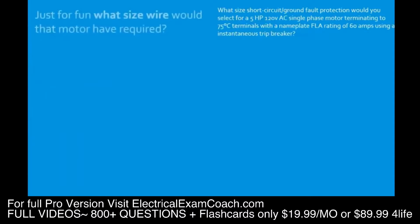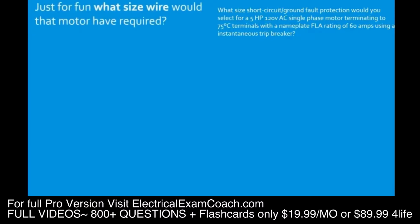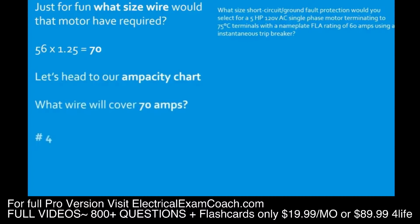Now, just for fun, we're going to take the same question and size the conductors, okay, and show you how outrageous this is. So we size the conductors like this. We would take that 56 amp FLC, multiply it by 125%. That's going to give us 70 amps. Now we head to our primary ampacity table. We size the wire. It's going to be a number 4.